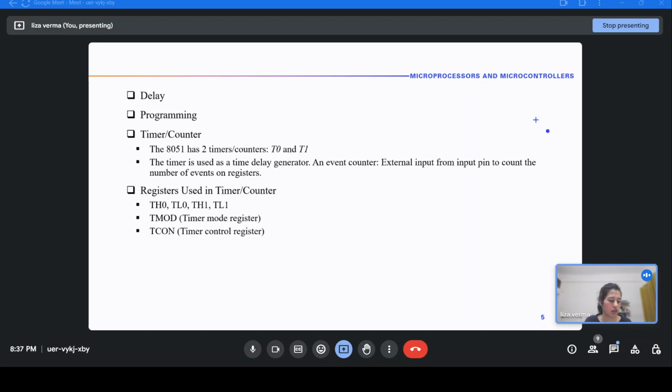All of the bits of TLX and THX are used. I forgot to tell you, the timer overflow bit is denoted by TFX. It's not your normal overflow OV, right? These TFX bits are in the TCON register; when you do those lessons, you'll find the TFX timer overflow flags. So M1 is a 16-bit timer counter. It can produce a delay of about 64K.